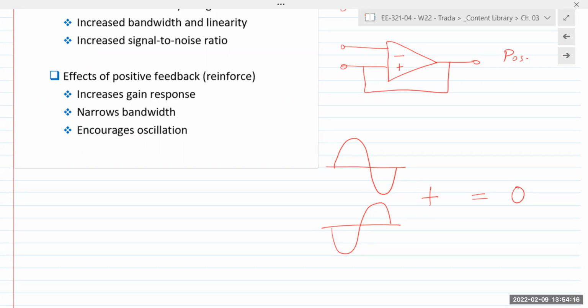Those captured sounds are inverted in phase by 180 and added back onto the input signal that goes inside the phone. When it's output to the speaker piece, it gets canceled out. That's basically how noise cancellation works.